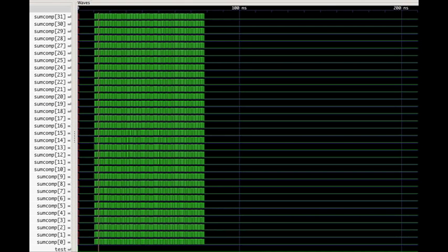So we're going to look at the waveforms of the shifters now. And we're going to look at them first in terms of their relative speed executing the test bench. And we're going to look at each one on the uniform time scale, 100 nanoseconds here. So we'll see how they compare to each other. So this is the first shifter with the bits individually closed or acknowledged.